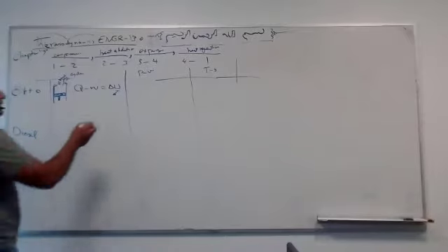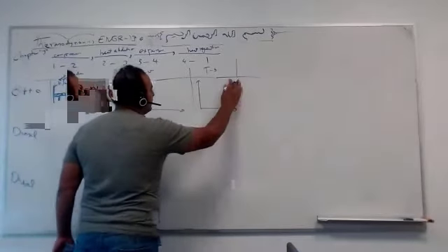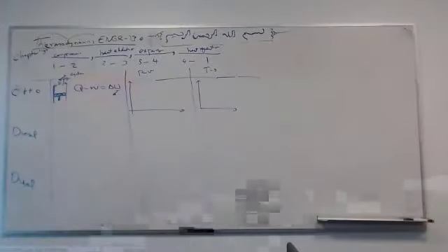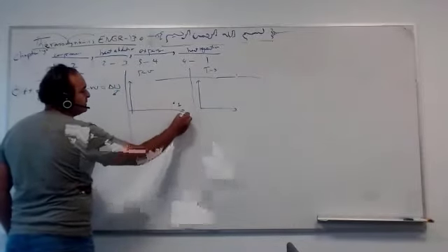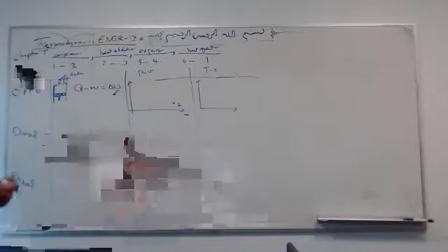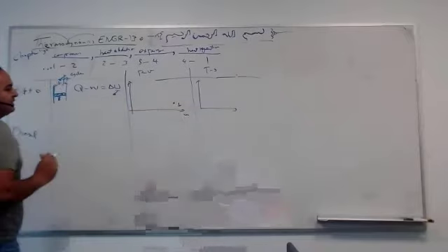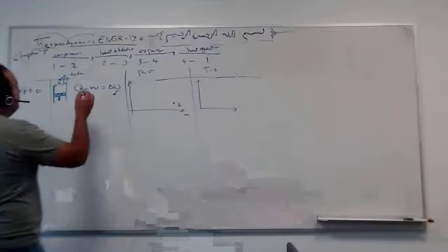Always. Let's draw the cycle. Somebody tell me from where to start in the PV diagram. Bottom left or bottom right? Bottom right, because usually we compress, so we need to give room. Pressure will build up and the volume will decrease, usually. If it's expansion, go to the left, you are right. But usually we start for all the cycles from bottom right. So we have first compression.